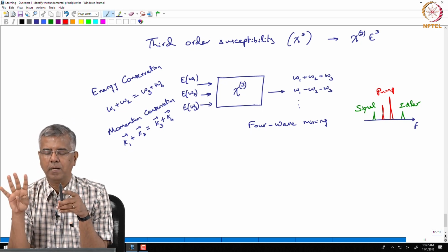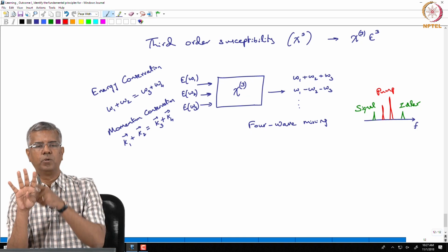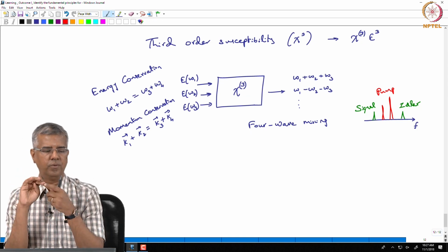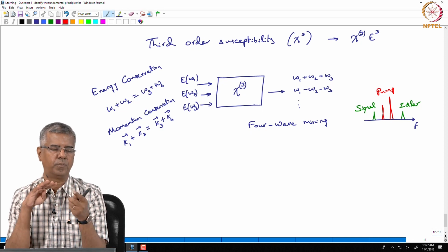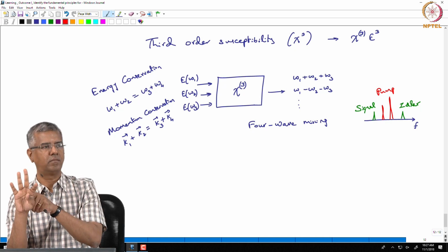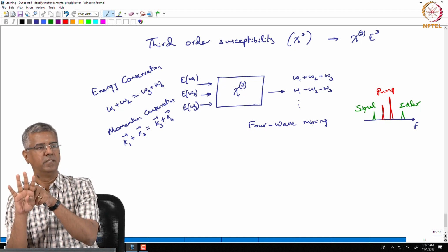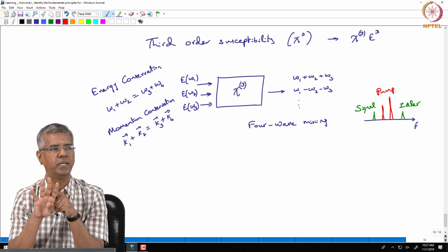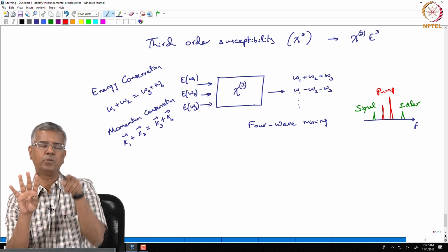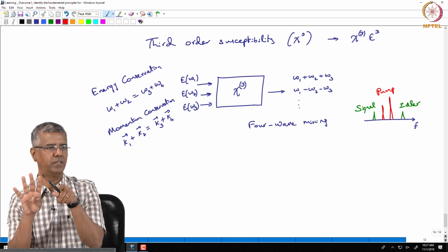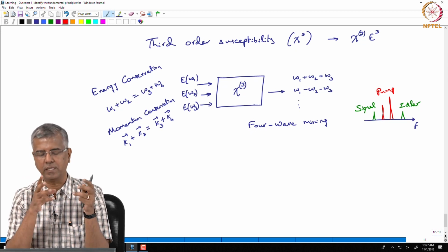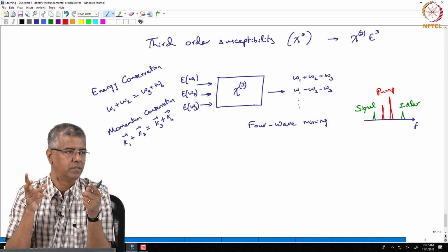And at some point you get to a node, and you find that the fiber in which these signals have to propagate is already carrying this frequency. So I cannot insert new information at this frequency. Whatever I have in this frequency, I need to transfer to some other frequency, some other wavelength. So that is actually called wavelength conversion.